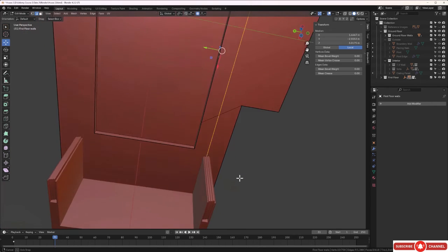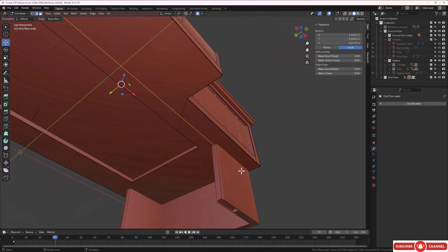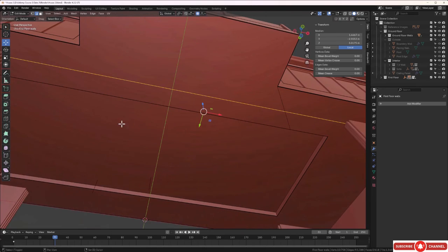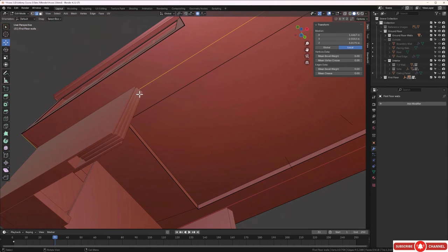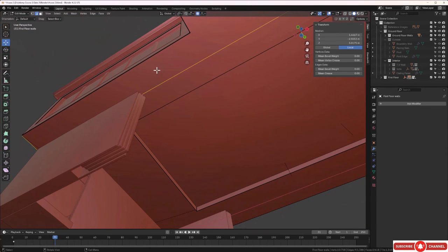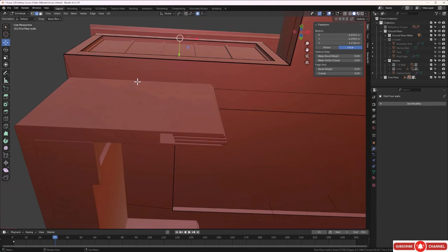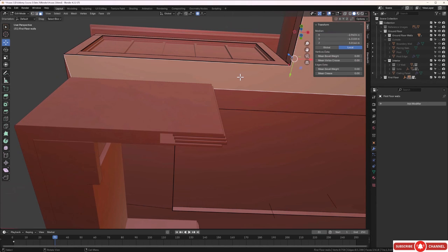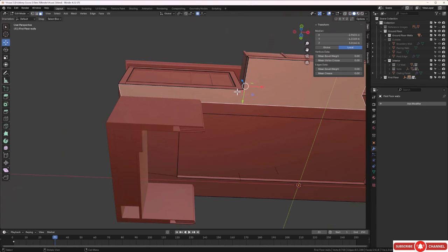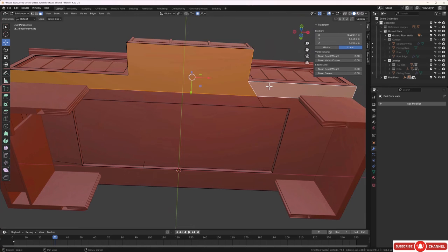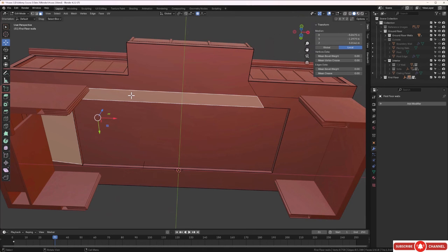And that has worked out quite nicely. That's pretty much exactly where I want that divide line to be. Sort of halfway across all the doors, so that this side could be like an exterior rendered finish, and this side could be paint, and that the door track will conceal what's in between. Okay, so now we'll just press 3, select faces, and make sure that we've done that. So that's working well there. We can select this one too, and yeah, it's divided these surfaces nicely.